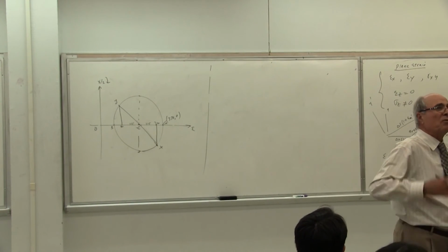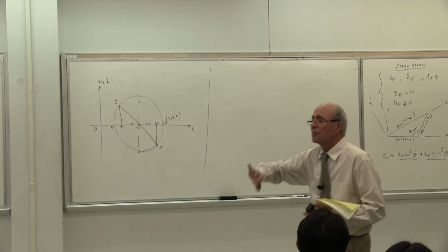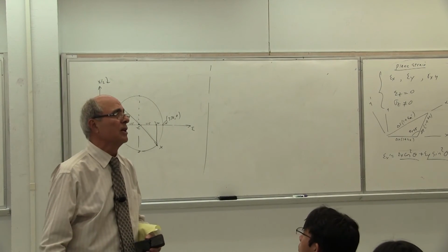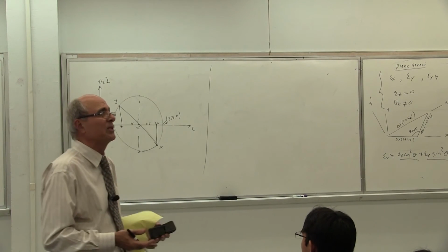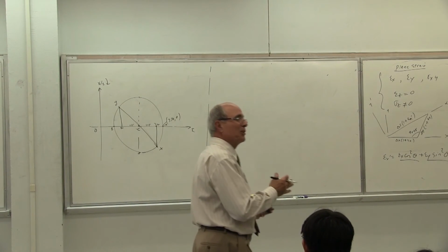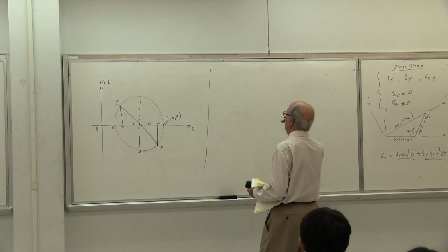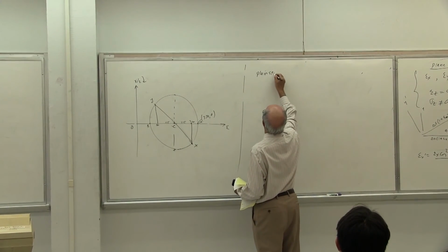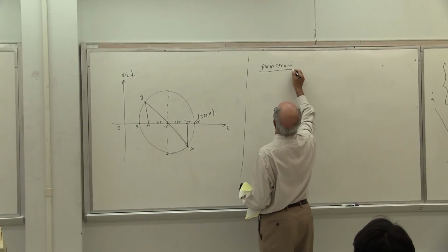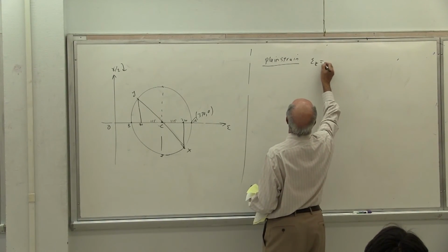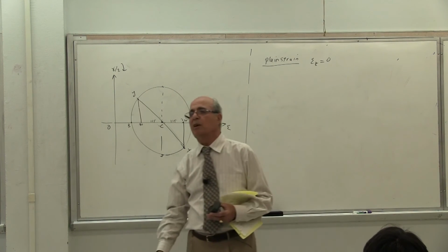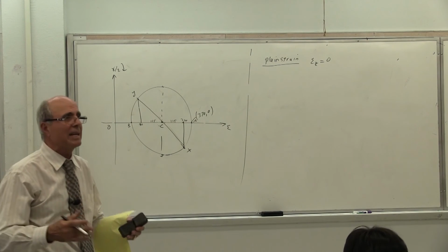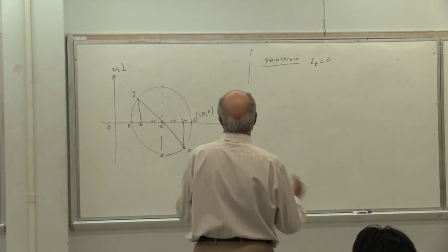Everybody understand it. When you are designing a beam, a column, the surface of a car, the surface of an airplane, is this surface exposed to the air? Yes or no? It is, so everything is plane stress. Everybody understand it. Reverse of the other one. So I want you to understand that. If the problem is stated as plane strain, then you say, okay, if this is plane strain, epsilon z must be equal to 0, as you were thinking. Is that correct or not? But that is a rare scenario. Everybody understand that. That's the reverse of the other one.